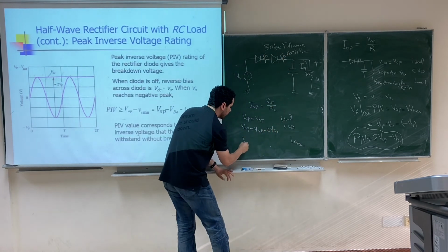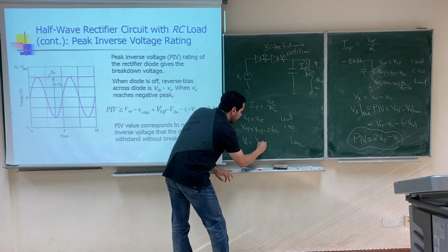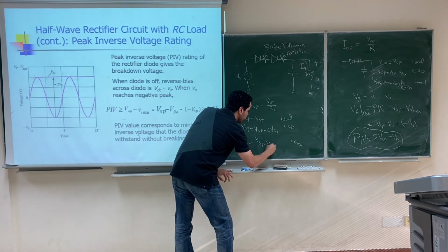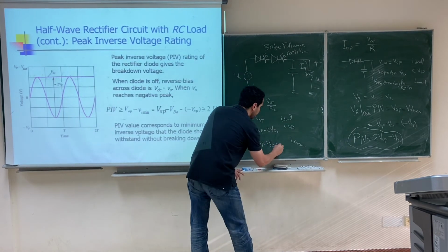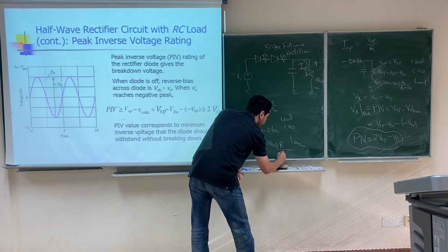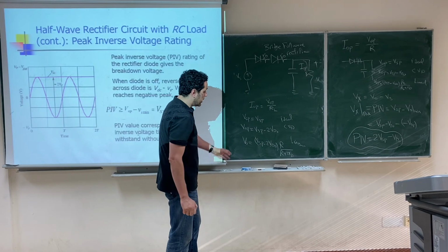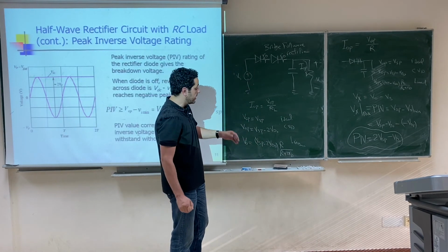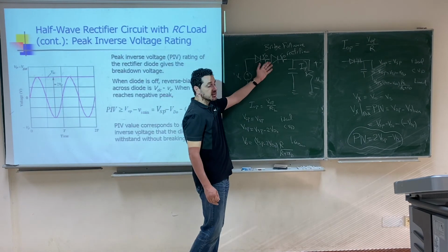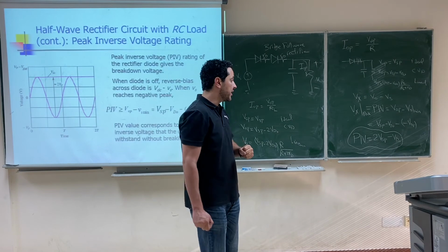In this case, V o peak, in the case of linear or piecewise linear model, will be Vs peak minus 2 VD0 multiplied by R over R plus 2 RD. Okay, so these will be the relations in case we have 2 diodes in the middle, and this example we will meet in the bridge full wave rectifier later.